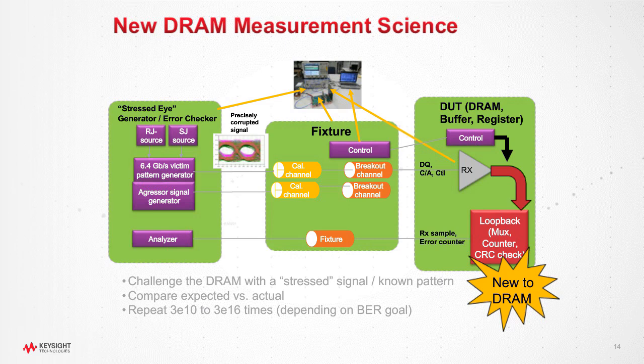And it's something that is important not only to make the measurement, but also because it involves connections at one of the most design and parasitic intensive parts of the system, which is the receiver and the PHY. Conceptually, it's a pretty simple thing to do, to add loopback. In practice, it requires a fair amount of preparation and work. But there really isn't any other way to characterize a design and verify it against the spec without this kind of receiver testing.